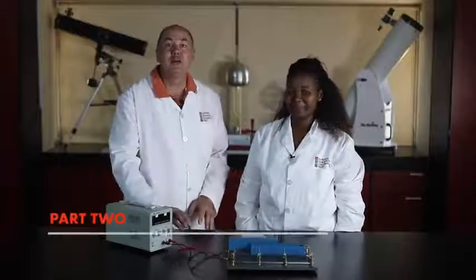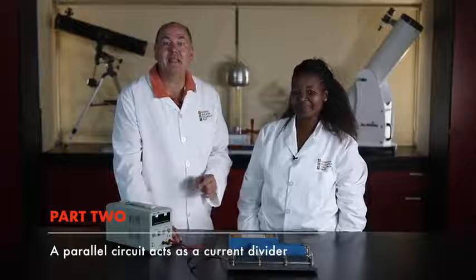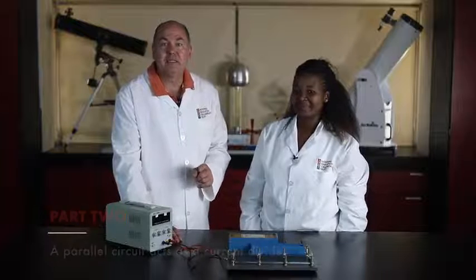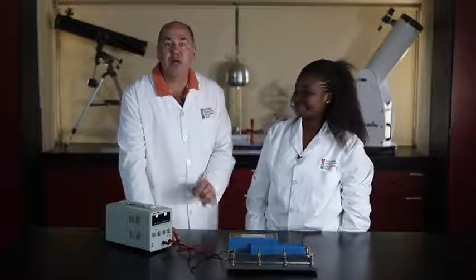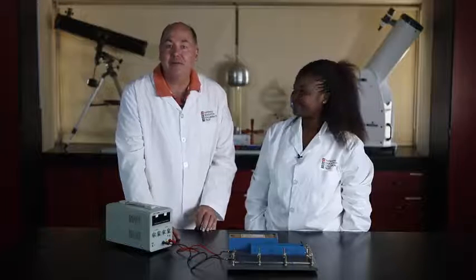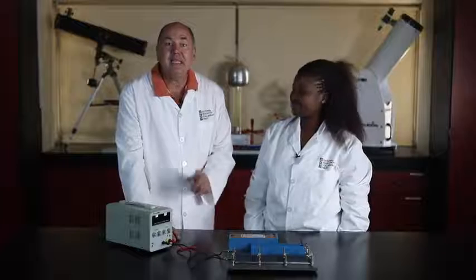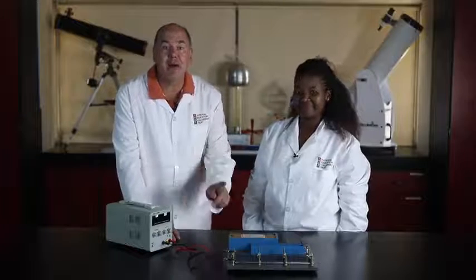Welcome back to part 2 of the experiment. We will now investigate how a parallel circuit acts as a current divider. The potential difference across a parallel part of a circuit remains constant. It is the current that divides up to pass through each of the branches of the circuit. Let's see how this works by looking at a parallel circuit.